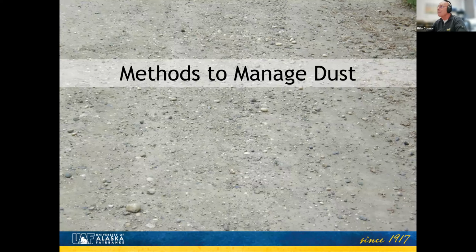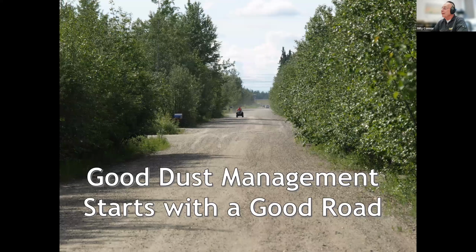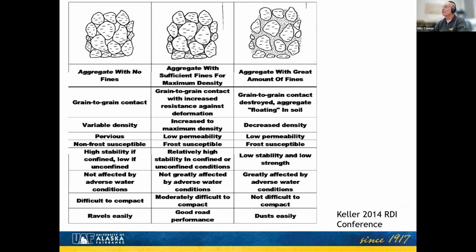So let's talk about some of the methods that we can use to manage our dust. Frankly, one of the best things you can do is build a good road. And we're going to talk a little bit about some of the things that we can do. Interestingly enough, we can reduce dust by adding dust, if you will, the fine grain particles.